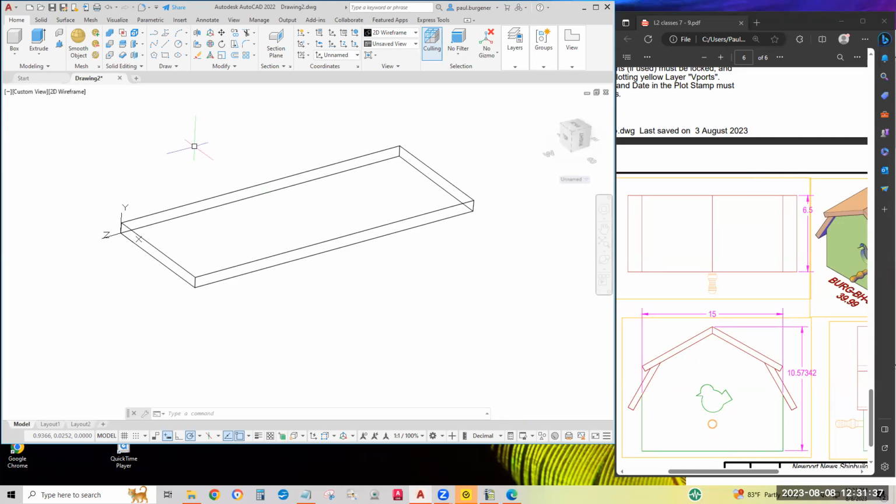So let's see, we can use a box. I guess let's use a box, or we could use a polyline. Let's use a box. I want to start the box at that origin. I'll click length and double check my cursor is perfectly in the x-axis. Length is now 14 by default. I'll click right here at 5.5 for the length. Now it says the width, that's the Y dimension, and I want to make it plenty high enough. I'll make it say 8.